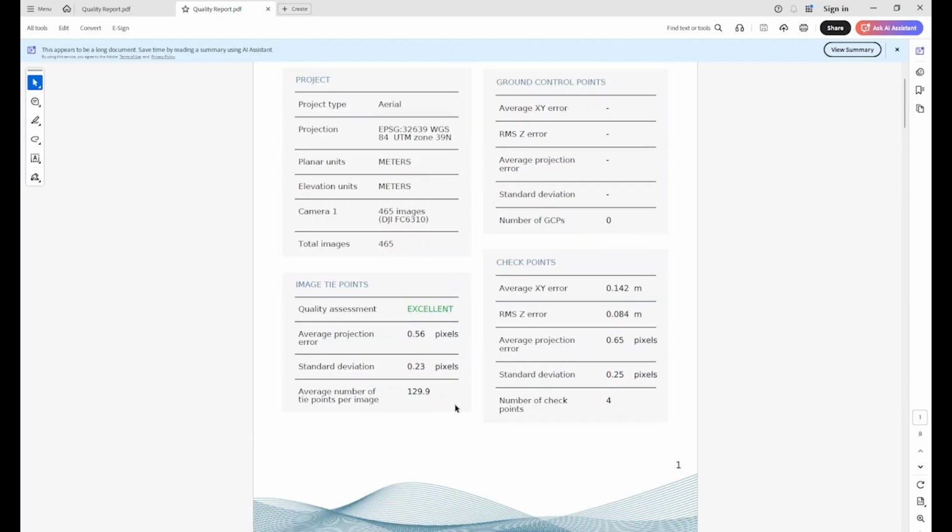So you get the best of both worlds. If you validate that this is actually RTK-PPK data, you import them as checks and you complete your checks and your quality assessment. And if it's not, then you always can default back to ground control points and use your ground control points to, again, tie your solution, improve your solution to a better absolute accuracy.